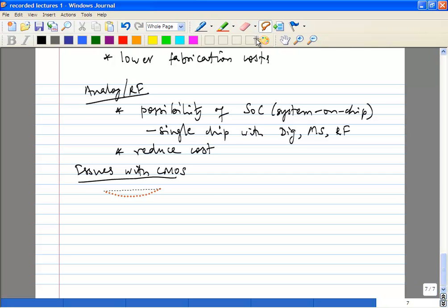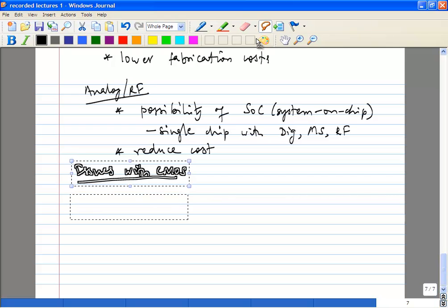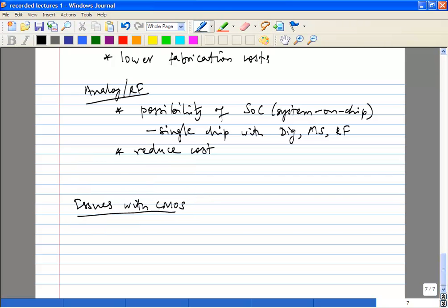But what you'll find is, as you delve deeper, you'll find that there are certain issues nowadays. Before you go there, let's look at one more advantage of CMOS for analog, which is they've become comparable to BJTs in fT, which is speed, and this is a little bit more controversial, but in some cases their noise performance is better.